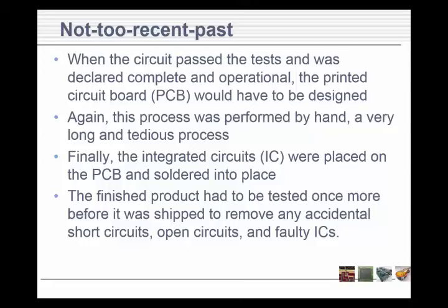So we'd make those. Imagine how many problems we could have with those, right? You could have it backwards, or as you were etching some of this off, the trace would break. So now you had to put a wire in place of it, and it just looked kind of trashy. So you had a lot of testing to do. Is it a short circuit? Is it an open circuit? Is it a faulty IC? Did you mess up the trace? So on and so forth.